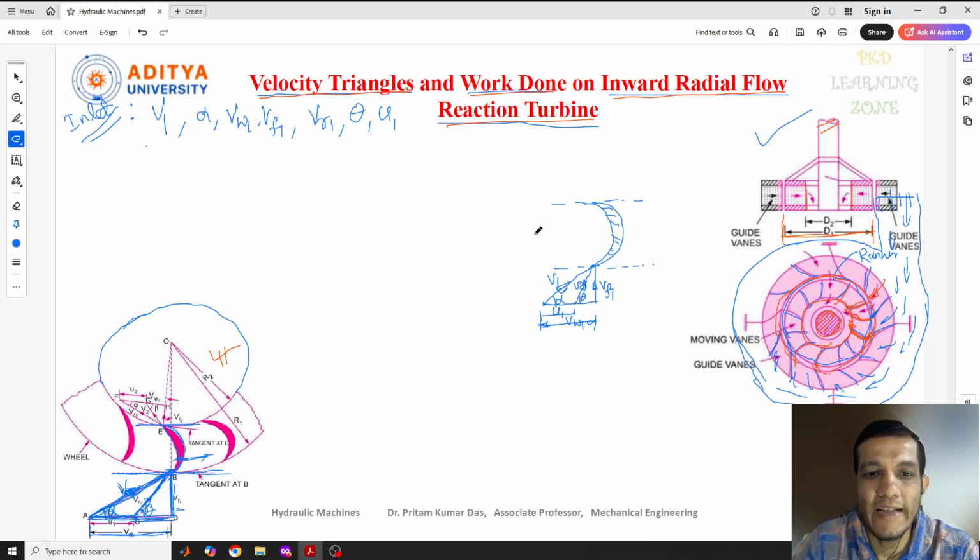That is the tangential velocity, I can say. This is the tangential velocity because you can consider it in this direction, which strikes the blade tangentially. We can also call it the peripheral velocity, or the velocity of the vane. The velocity of the vane is considered U. It is the inlet condition: vane velocity or wheel velocity, the tangential velocity of the wheel at the inlet condition.